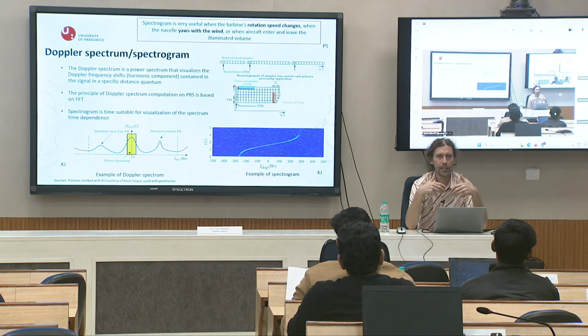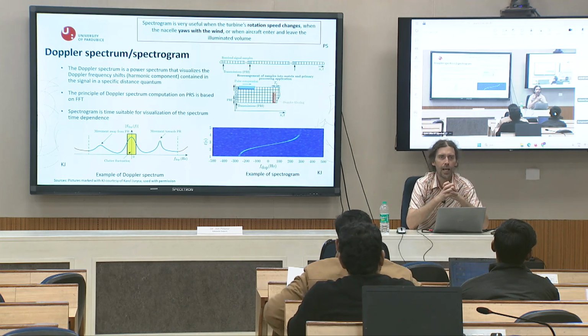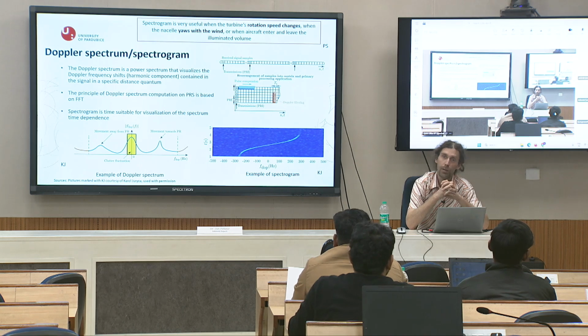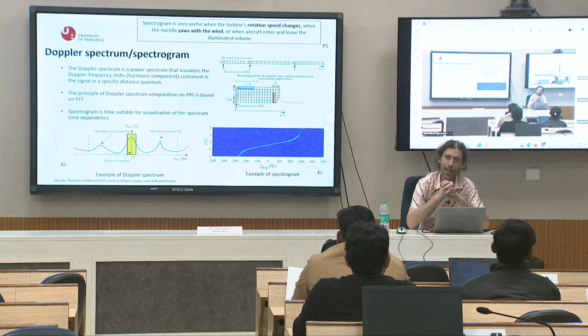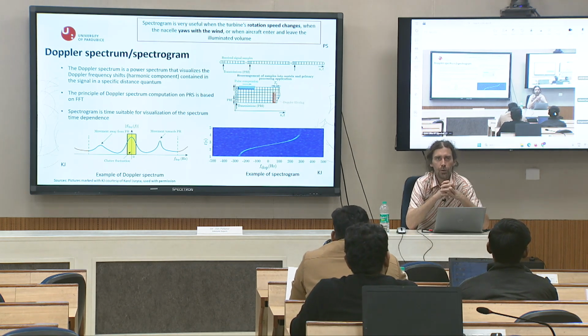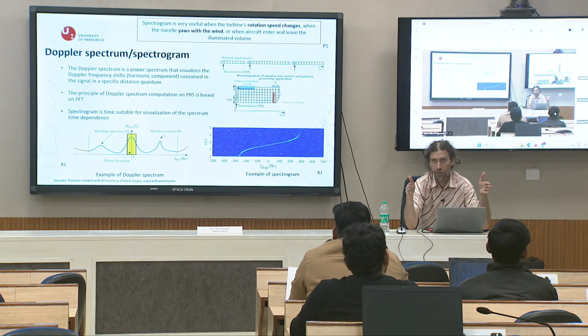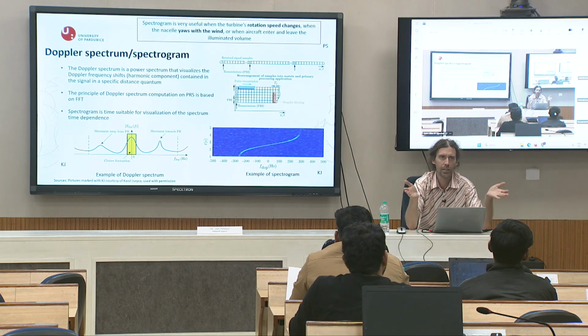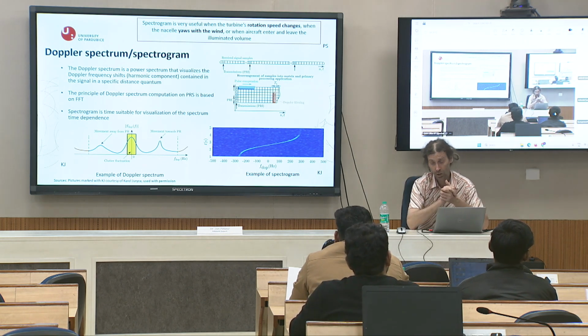And it is another problem. Then you design a mitigation technique, everything, and now you want to apply it to a real system and discover that your algorithm stops working. Why? Because aliasing occurs due to this high speed. And how can you influence it? Increase the PRF. But very often the radar is already designed and is already in an environment. You can't just change these input values.